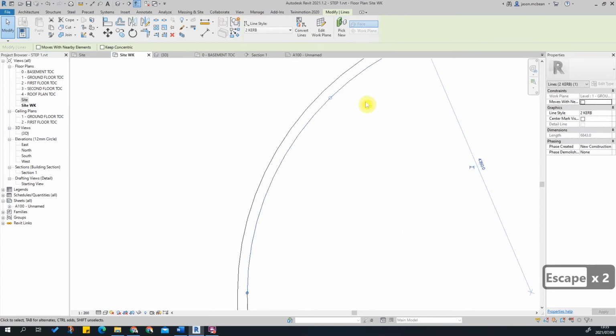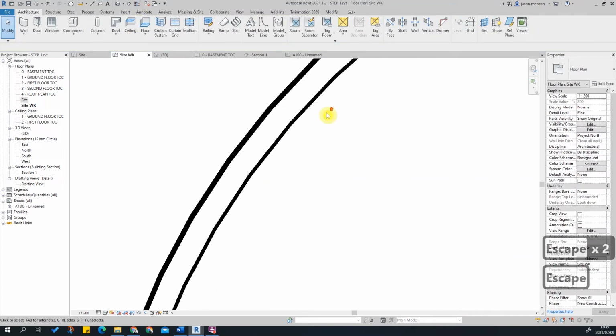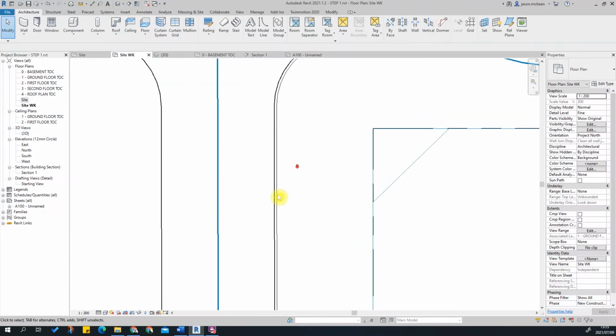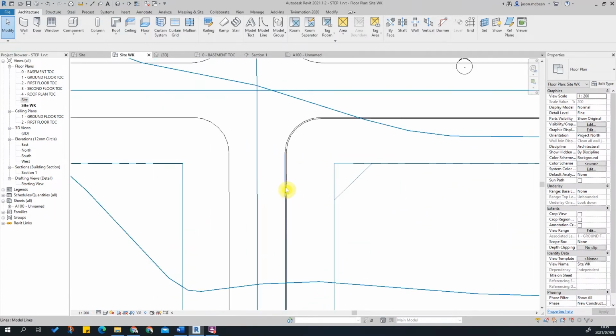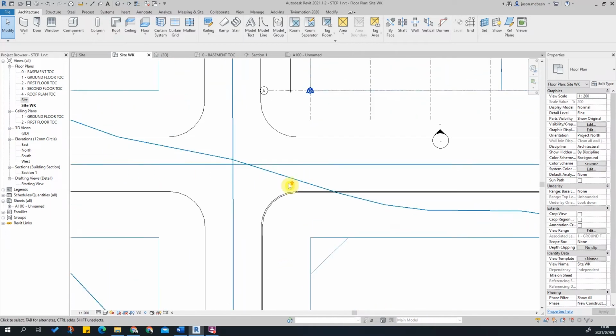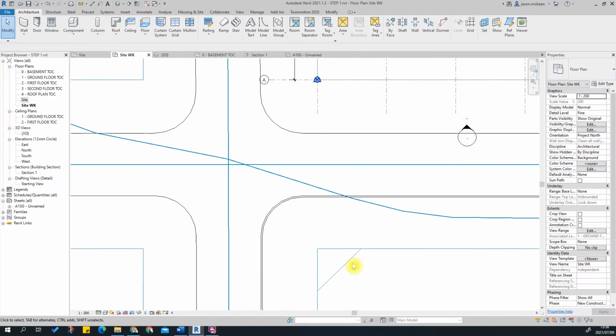Okay, so that's worked pretty well. If I switch on my line weights, we can clearly see a hierarchy or definition. So the road line is more important than the curb line. The curb line is purely just to indicate where the curb occurs and how it works. So I'm quickly going to go around and complete the offset of all the other line work.